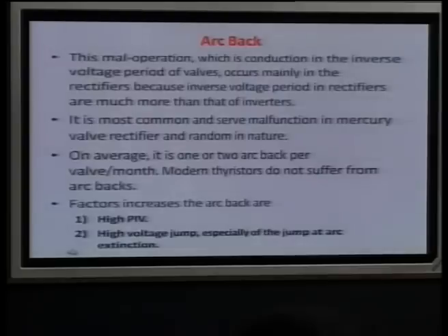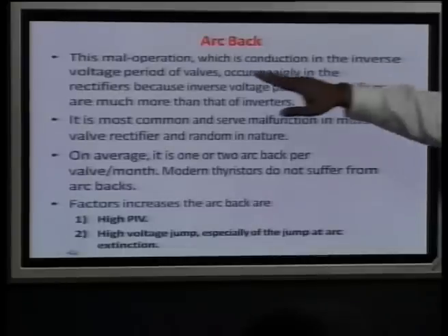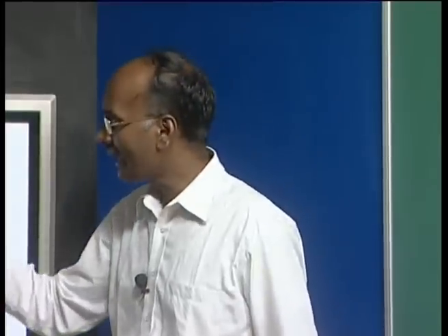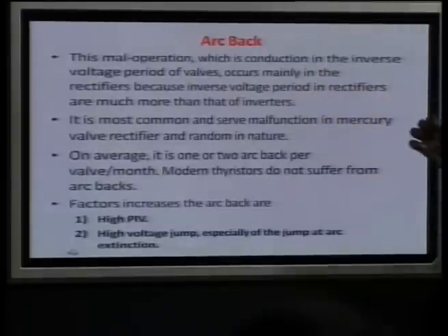So, let us see the arc back. This small operation, which is the conduction in the inverse voltage period of the valve, inverse voltage meaning the voltage is negative, occurs mainly in the rectifier, because this inverse voltage period in the rectifier is much larger than the inverter operation, as we saw.